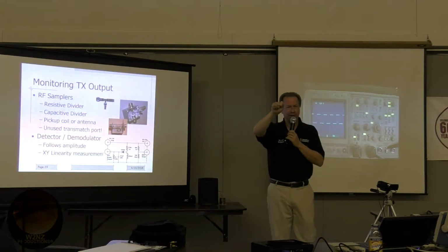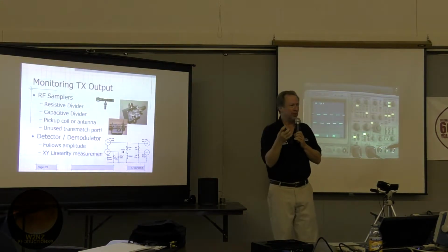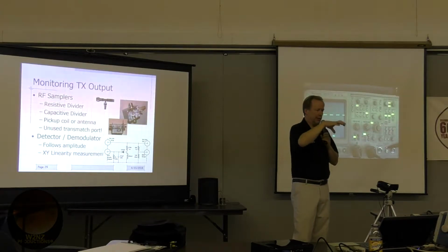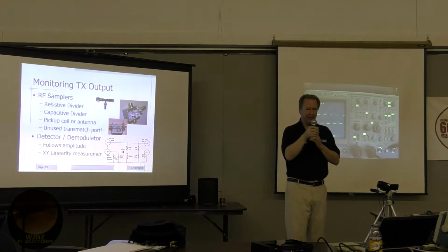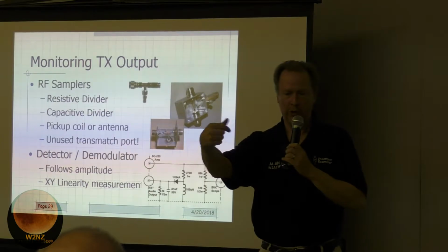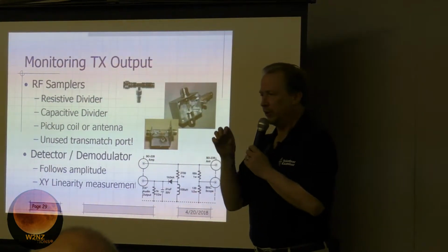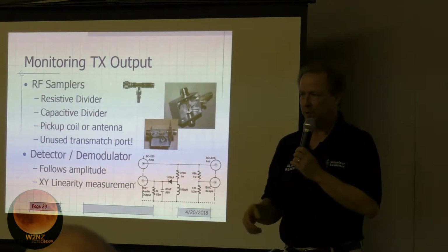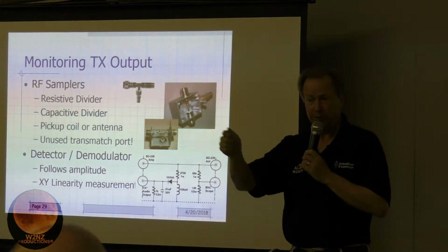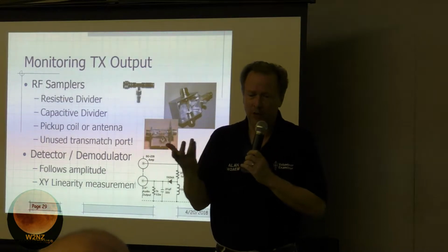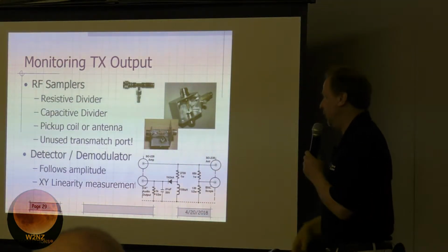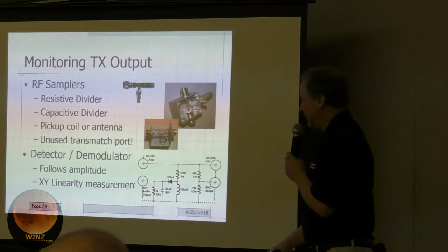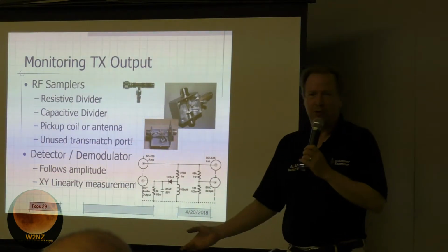Switch the transmitter to the antenna you're normally going to use, but there's often enough coupling inside that metal box that even though that terminal's only going up to the switch and going nowhere else, you get enough signal coupled onto it to go into a scope. That's dangerous. Well, you just don't switch to it. You let the smoke out of the scope. But it's a neat little trick that doesn't cost. You don't have to build anything.